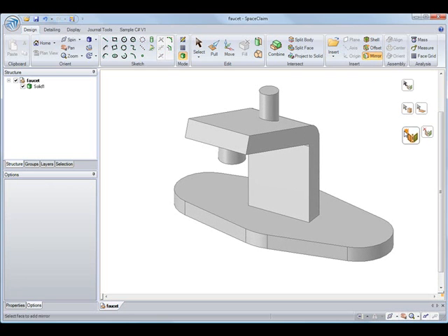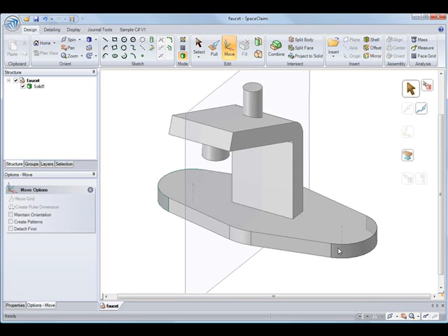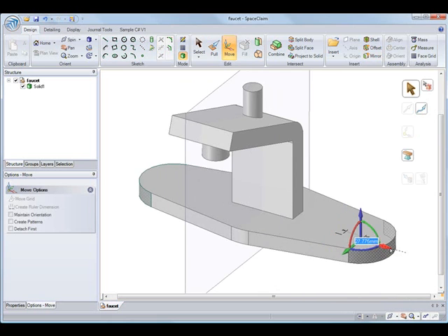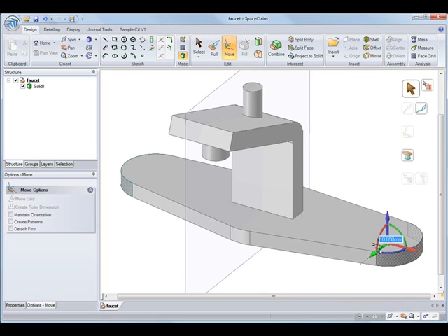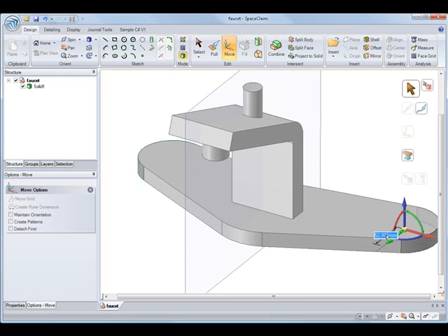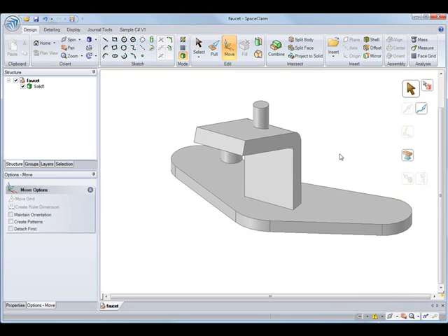First, I'll click this button, and then choose two pieces of geometry, one on one side, and then next on the other, and you can see the mirror plane pops up. And that creates a relationship between these two surfaces. So we can see if I move it to the right or move it back, those stay the same and all the geometry in the middle updates accordingly.